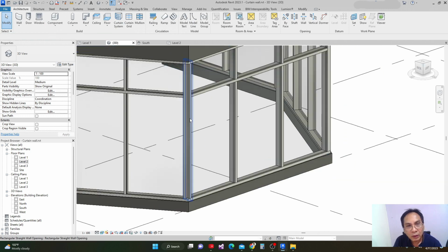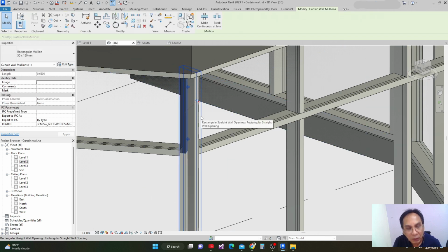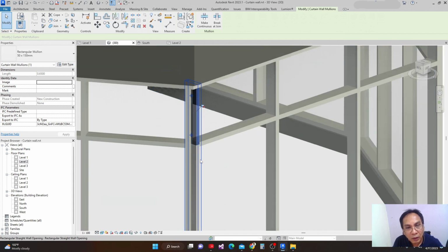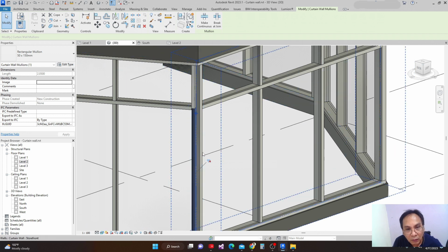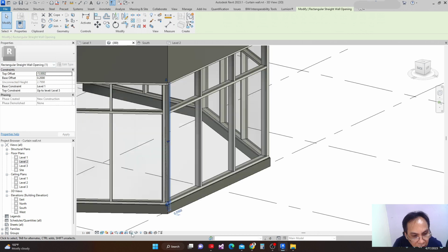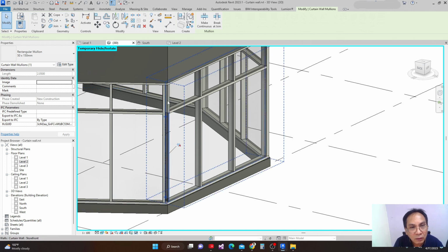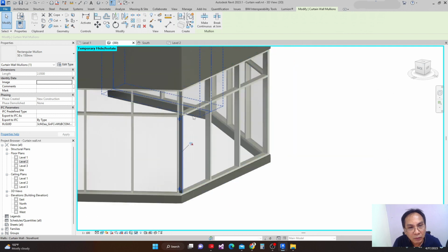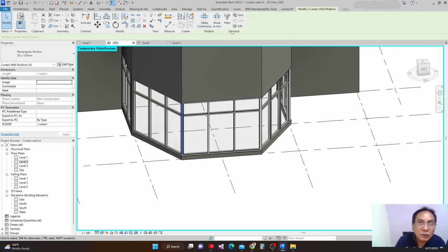you can see both, and what I'm going to do is I select this one mullion here and unlock it, another one mullion here, tab, and then unlock it, and then these two, unlock it, and then the other one, unlock it, and then I'll select both, and then hide element, and then both of these and this one already locked. Okay, maybe go back to